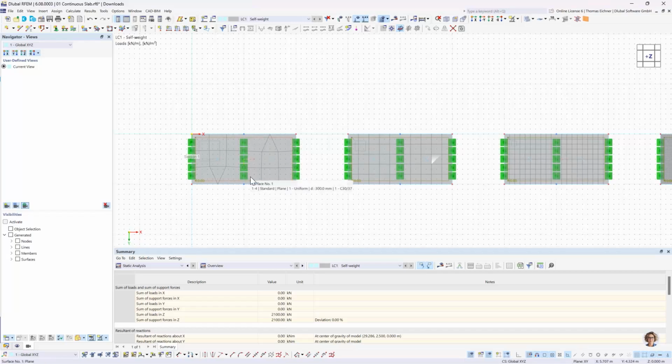So in the first model, with our 2 meters length here, that's quite coarse. And we also see we even have here a triangular element, which is also not perfect, since it's just better to have a uniformly distributed rectangular finite element mesh. Sometimes it's not possible to evade those triangular shapes, but if possible, you should try to avoid them.